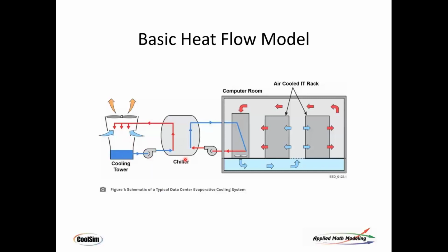These configurations can change quite a bit. For example, there could be a bypass plate and frame heat exchanger that goes around the chiller so that on certain days you can use what we call economizer mode, where you just go through the cooling tower by itself because it's cold enough outside that you don't need a chiller, you don't need to do compression. And then there are variations thereof, sometimes called trimming, where you use a little bit of the chiller, but mostly the cooling tower. Those are more complicated scenarios, but I want to point out to you that when modeling these things in a transient case, you need to know all that stuff. You need to know what's going on out there in order for you to define the problem correctly.